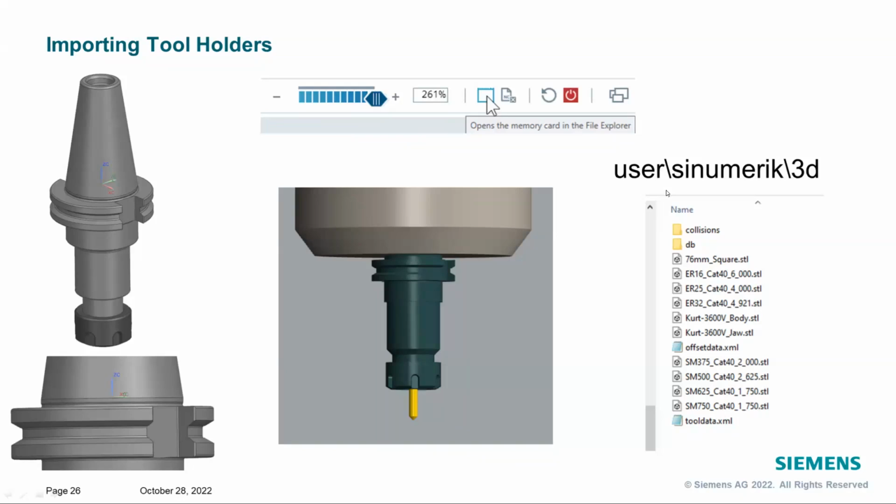But you also want to verify where the datum of the tool is. The tool zero, which you see with this little UCS in the picture, should be at what we call gauge line. On a CAT 40 tool, gauge line is about 1/8 of an inch off the top of the flange, and it's going to be dead center. It doesn't matter which direction X and Y point in, as long as your zero is in the middle, and in Z it's right at this gauge line point, that'll give you the correct connection point in the machine.